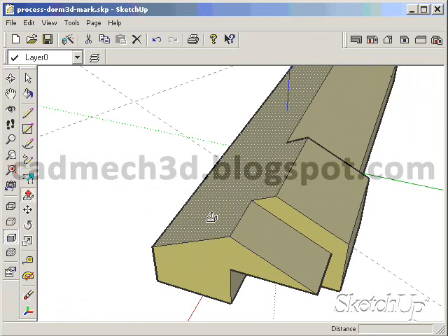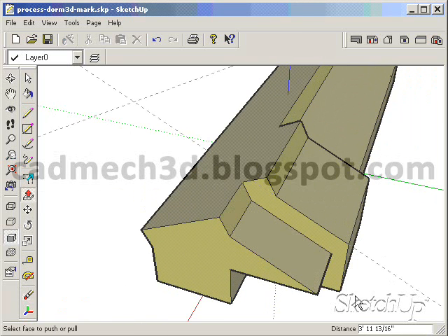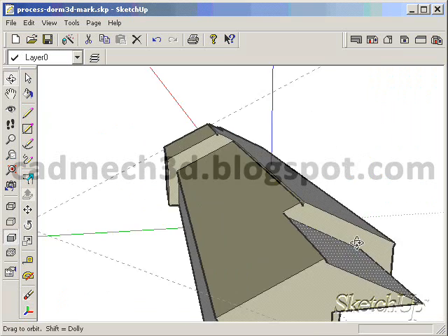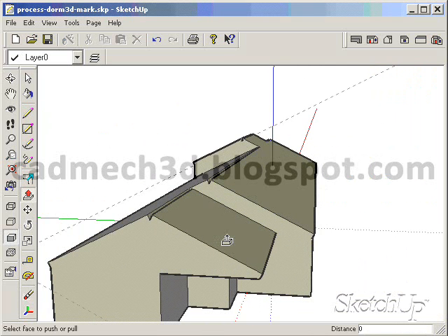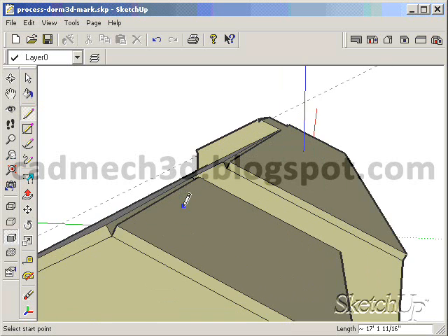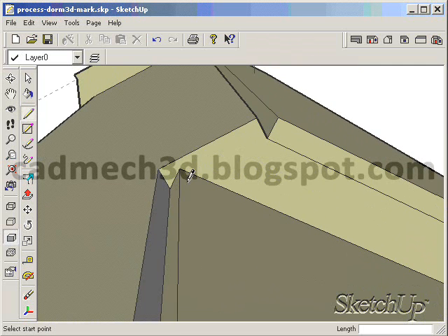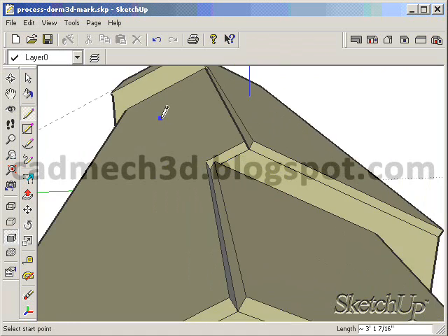Now we can add depth to each area of the roof. This will create surfaces I can extrude for rafter ends. I'll start by extruding with push-pull one roof surface, and I'll type 8. Now by double-clicking on each successive face I can repeat the last 8-inch amount of push-pull offset. Now taking the pencil tool I draw in edges connecting the lower part of each push-pull surface. This will create faces I can use to pull out the overhangs at the gable rakes. I do that all the way around the roofs on every segment where I want to create an overhang.